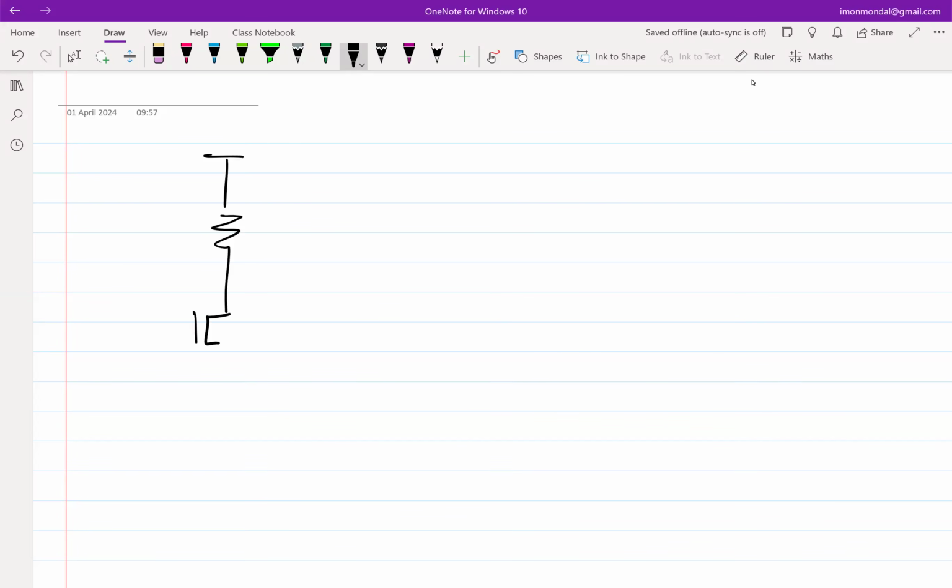This is an NMOS equivalent of a common source amplifier, and this probably was good enough to achieve any gain, provided you had access to as high a supply VDD as you can. However, the problem that we saw was this transistor is not an ideal voltage controlled current source in the incremental domain.